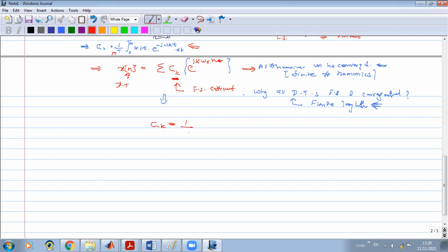In case of a discrete time signal, it is the number of samples, measured as a value, like 1, 2, 3, 5. But you may remember that this point we can map with time: nTs, the time point related to the nth sample.